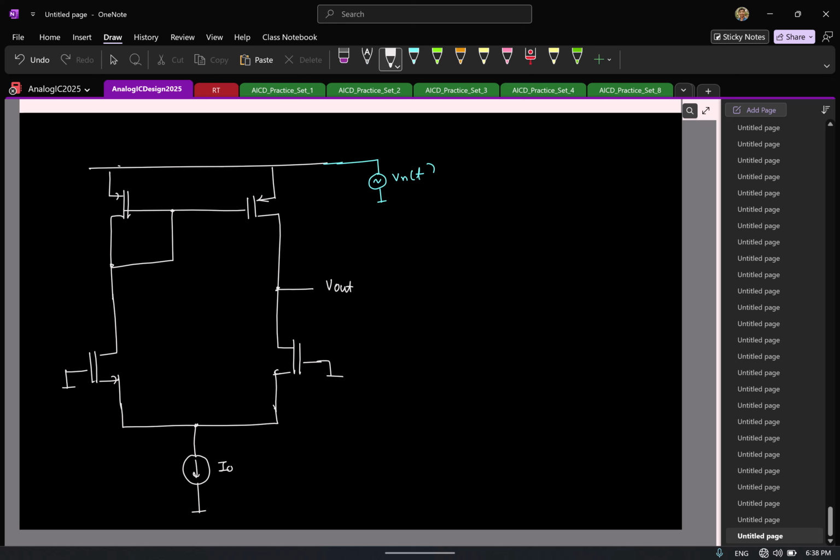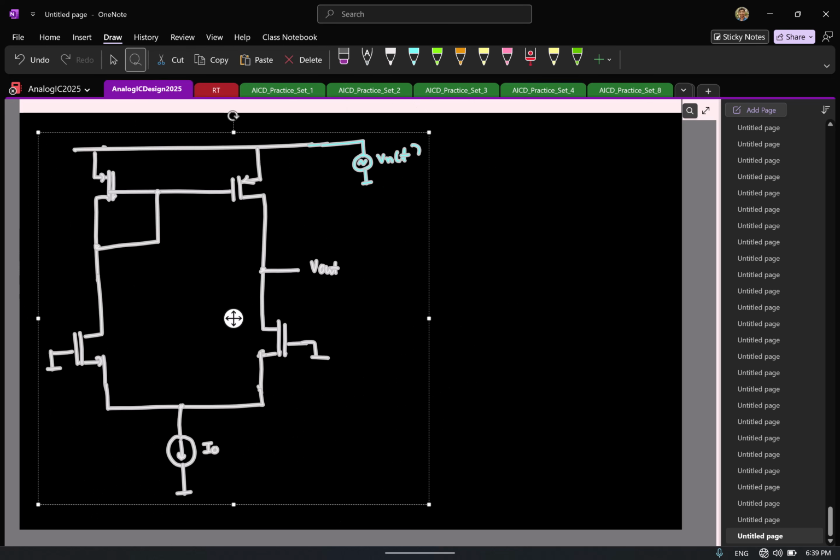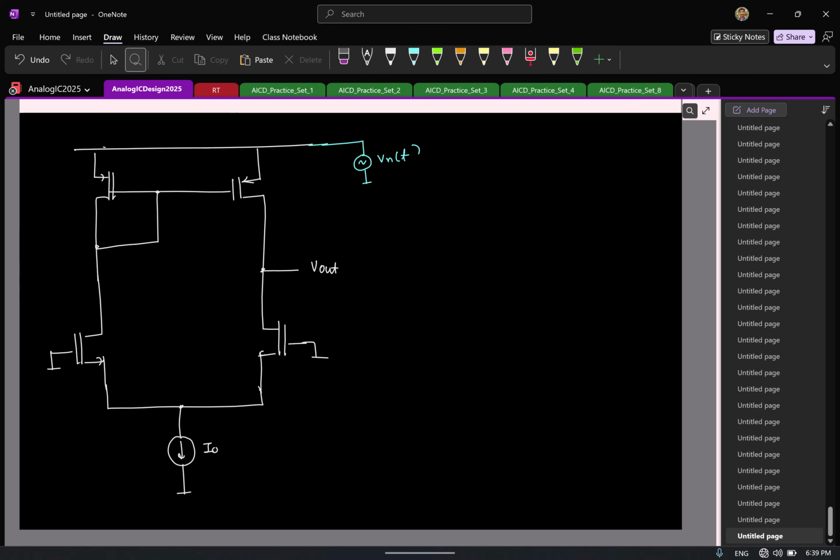How will you find it? Yeah, you do small signal and then you use KCL. Yeah, you can find the short circuit gm and Rout, nice thing. But again, remember we have looked at this 5T OTA for such a long time. So is there something you can do to simplify this further? Can you elaborate? Yeah.